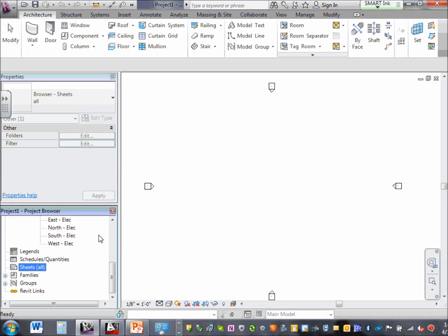Pages, yeah. Drawings, pages. Families. In Revit, one thing you have to understand, the difference between Revit and CAD is, in Revit, the symbols that I downloaded for you guys, instead of symbols, they call them families. So if you need a receptacle like that one there, they call it a receptacle family. So get used to the word family, and the family has members in it. And the members of the same family can be slightly different.